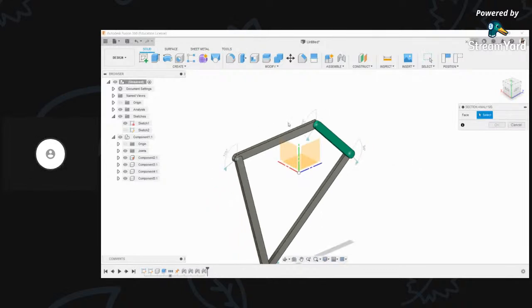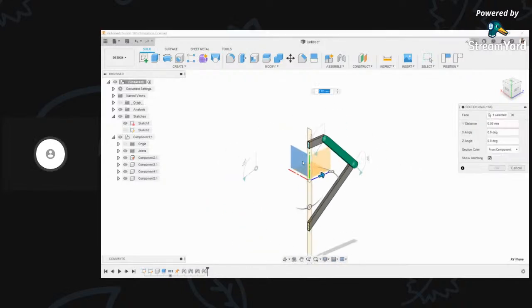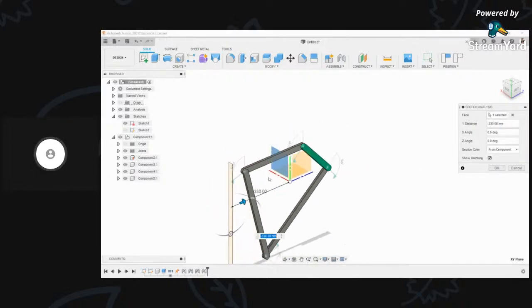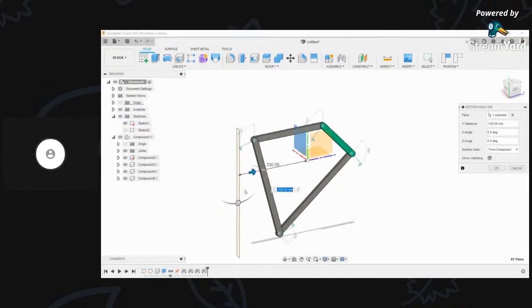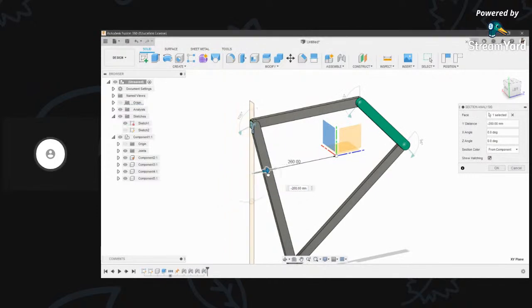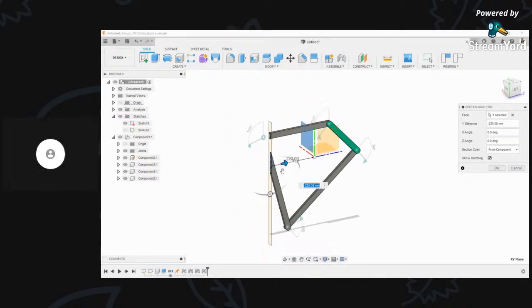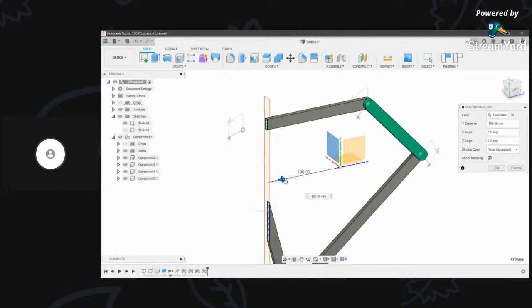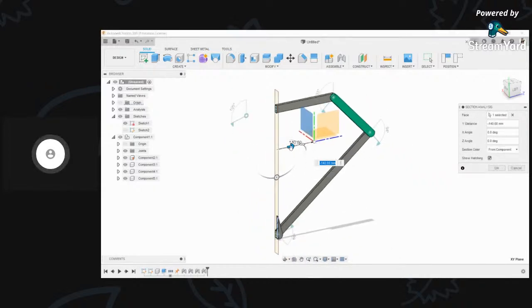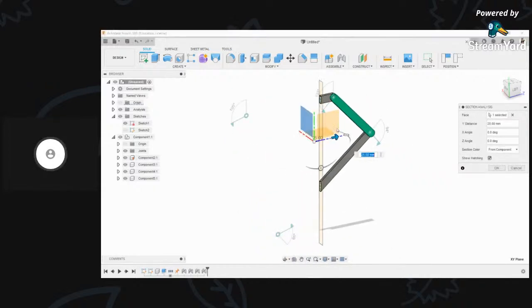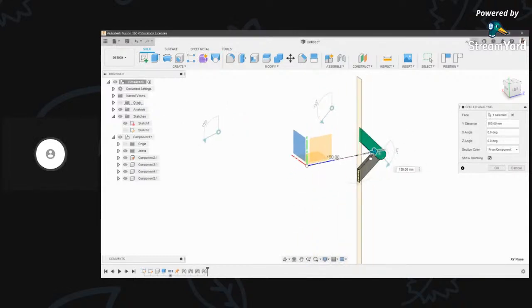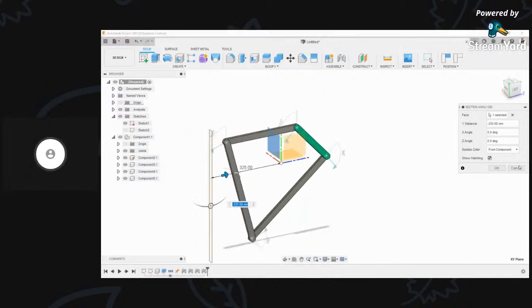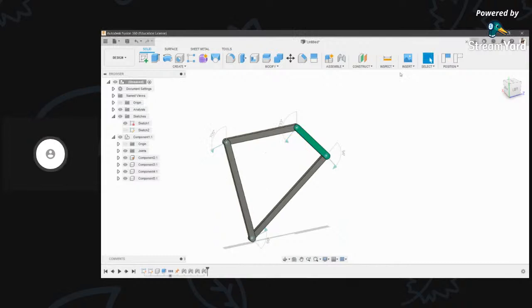And then we have section analysis. Yeah, section analysis is very good. So you can use this option to analyze in between the section, like if there are any defaults and all, you can just change it. So if you drag your mouse, you can see it will start showing me the section analysis of it. So you can use it to analyze if there are any faults in the section. It will just go like this, and it will again come back. So this is a section analysis. It's very much useful. You can use it in all your models.